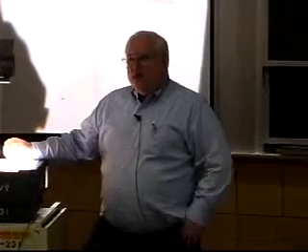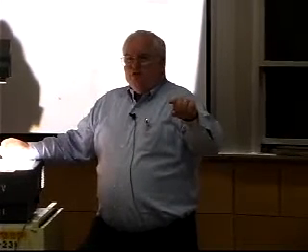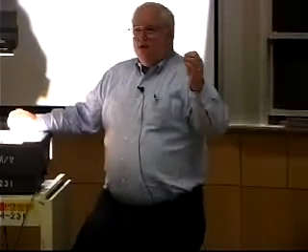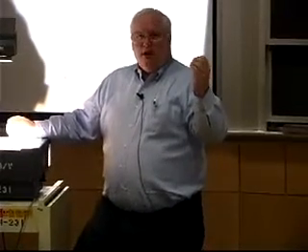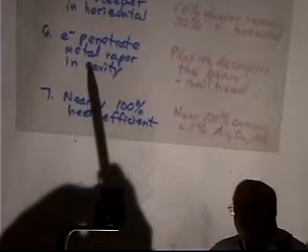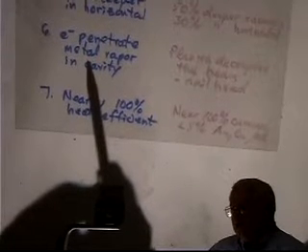It turns out these high energy electrons will penetrate the metal vapor in the cavity. An electron with 50,000 electron volts is not going to be stopped by a single collision with a gaseous metal atom, which has a thermal energy of 2 or 3 electron volts. 50,000 versus 2 or 3, 50,000 wins most of the time. You have to have hundreds of collisions before you slow those things down. So you get pretty good penetration of the beam down into the hole, which means the electron beam per watt is going to give you deeper penetration than laser per watt.